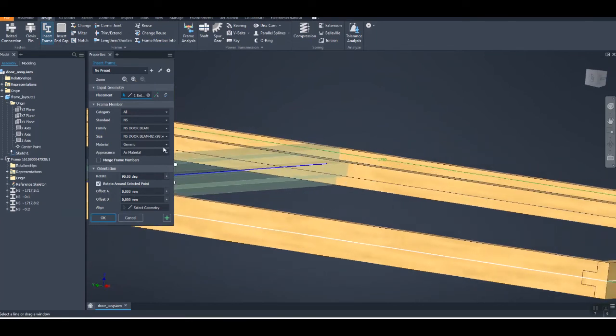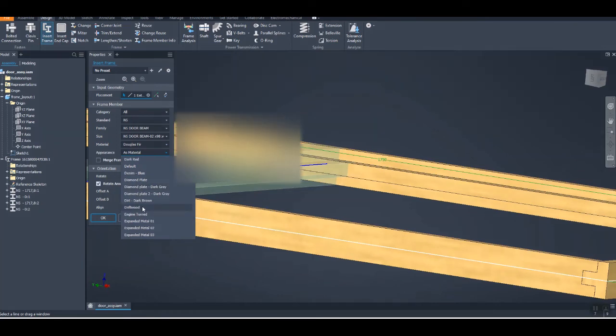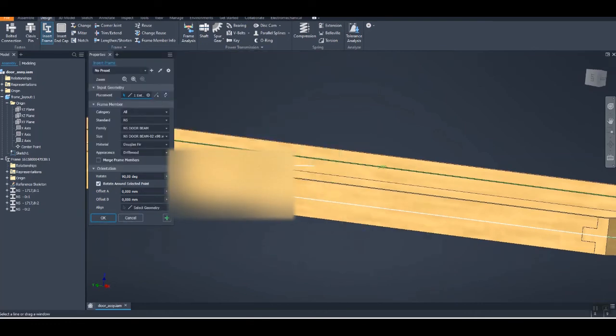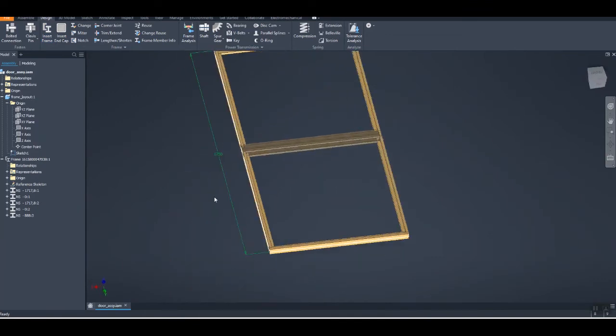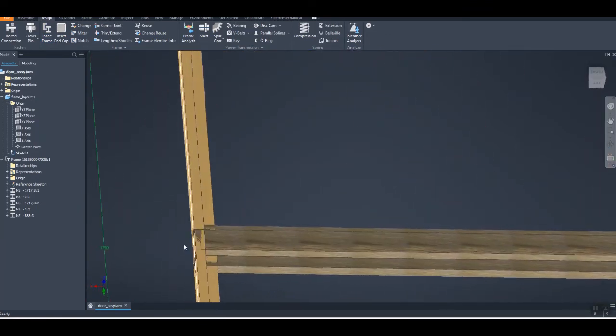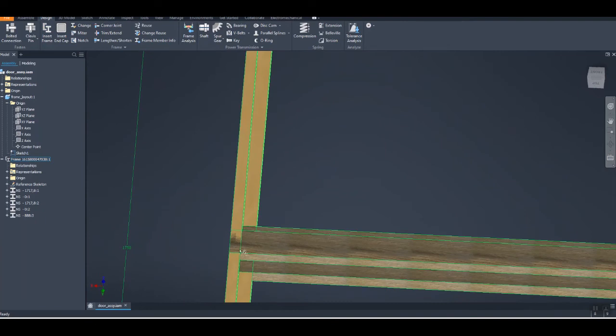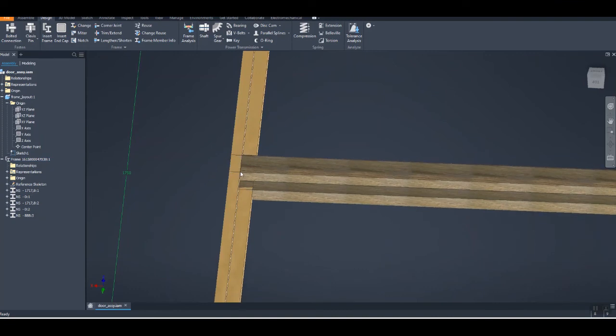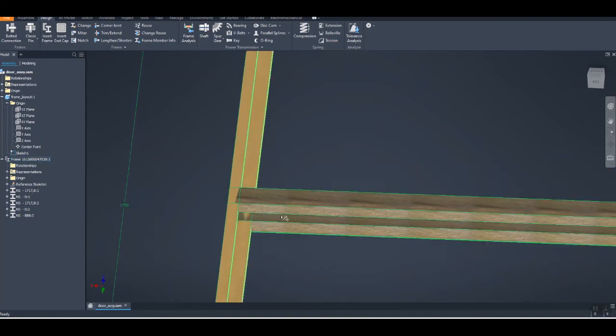Let's see here. Now if I just select the material, I'd take Douglas fir on this one too. Appearance, we could change the appearance on this. Maybe it's good if we call it, I don't know, driftwood maybe. So there's the last beam there. You got a driftwood cross beam. This one, now you see how it's blinking here. That means that it's interfering with the side profile. So I need to notch this center one.